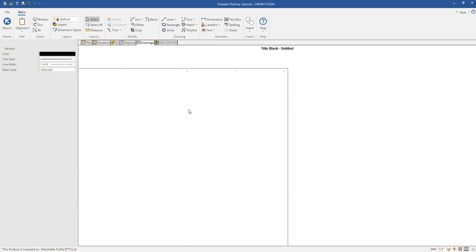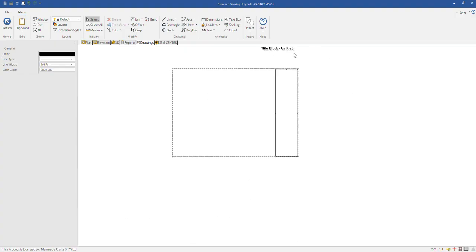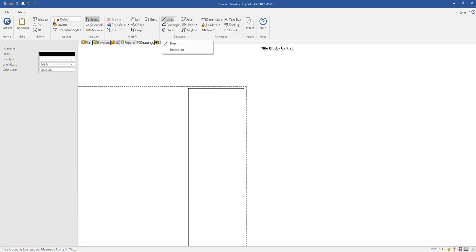I want to add a few different sections within that. So what I'm going to do now is select line, and from the drop down just select the normal line. I'm going to press there, let it snap, drag to the right, let it snap again, and then press select again there on top. Or what you can also do, instead of pressing select, is right click and then select on top. There we go. It removes the line snapping so it doesn't accidentally draw it.